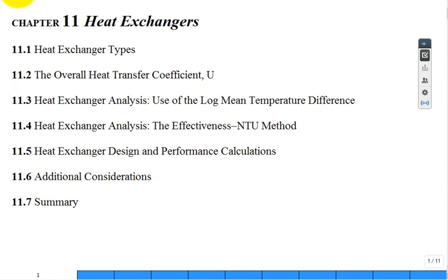All right, so we're in this chapter on heat exchangers. This is our second and last lecture in heat exchangers, chapter 11. We covered a lot of ground. There's two methods for analyzing heat exchangers. One is the log mean temperature difference method. That was the preferred method many years ago, but basically the effectiveness NTU method is the method emphasized in this chapter and a lot easier to use in practice.